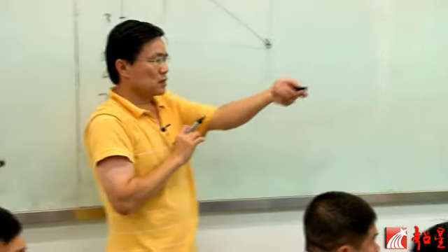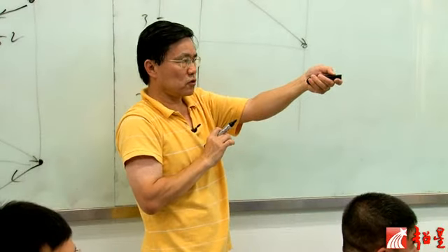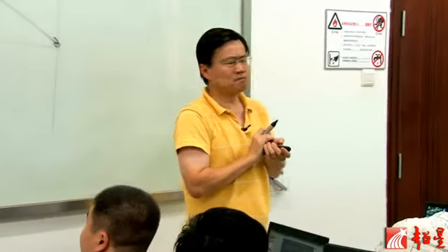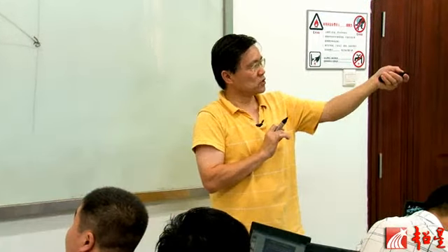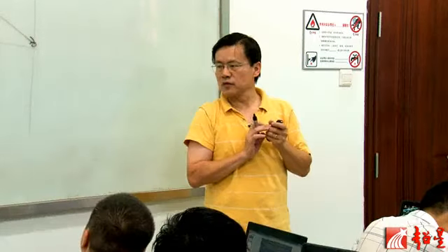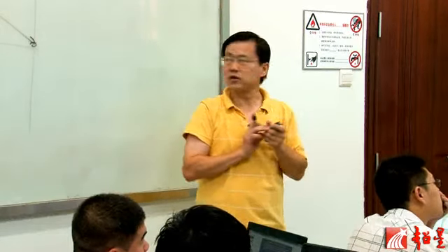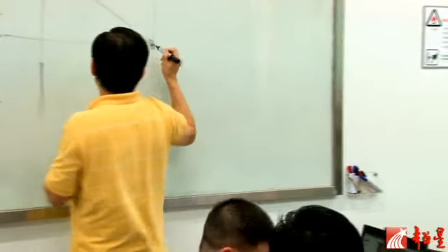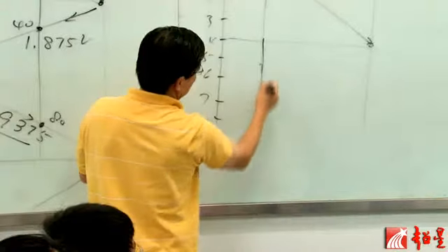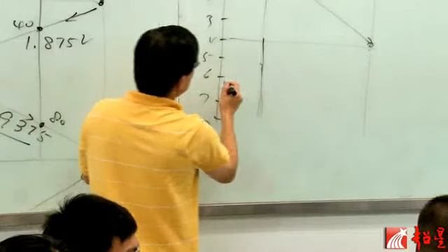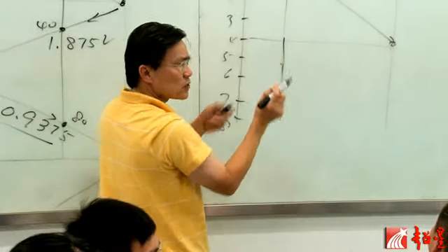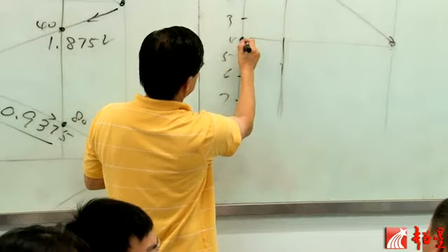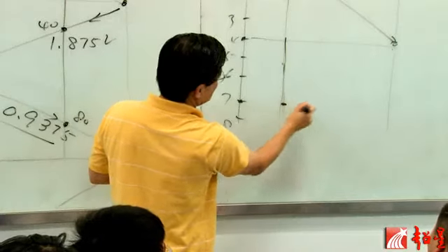Then there's a reflection coefficient at a point. What is the reflection coefficient here? It's just 1/3, right? Positive 1/3. So that positive 1/3 reflection will go, and it takes 3 nanoseconds to reach the middle, so it'll reach the middle at 7 here.